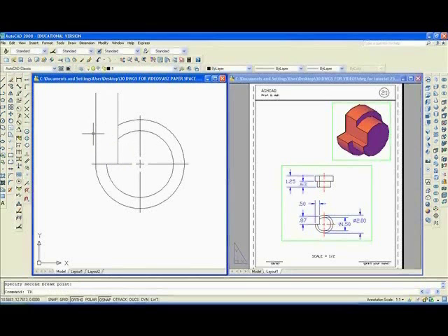And we want to trim, TR, enter. I want to trim from there that line and erase this line. Also, we want to trim from that circle, that, escape, repeat the command. I want to trim from that line, that, and the drawing looks more or less correct.